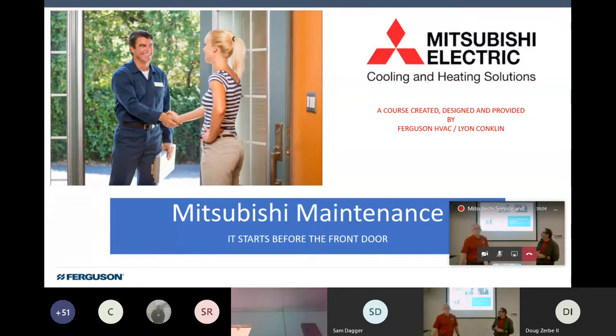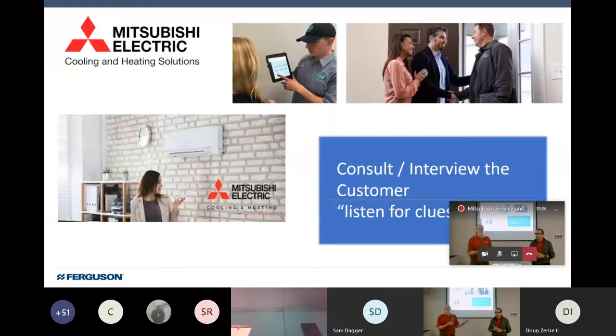One of the first things we want to do when we walk into the home is what we call interview and consult the customer. This is just to confirm why you're there exactly, especially on service calls. I've been out there on a no heat call, and that call may have come in over the night, back in my day through answering services, I guess we still have them. Somebody in the office got the message and sent it to the dispatcher, who's now sending it to you. It's like whisper down the lane.